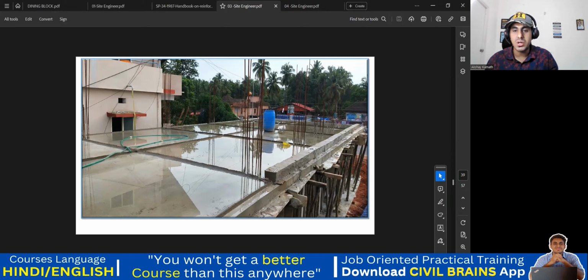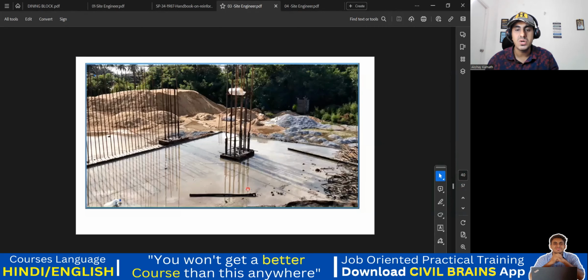Next day when you start the concreting, since you have created a kind of depression, your concrete will go inside this, and because of this a grip will be created, and not an issue. And anyhow, you have stopped at the point of contraflexion, where your bending moment is very minimum, so no failure or no cracks will happen. So that was the entire concept of the beam. Understood? Understood how it has to be done?